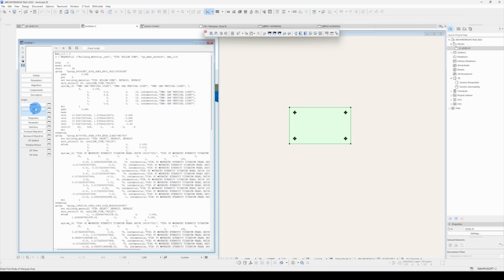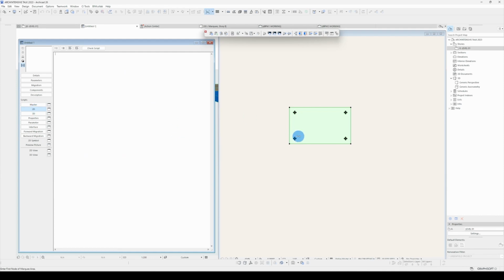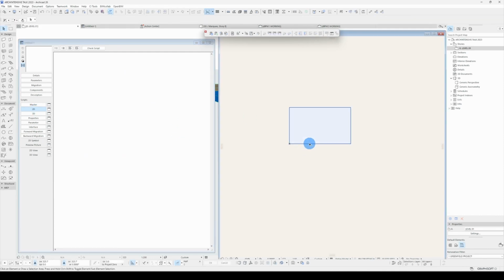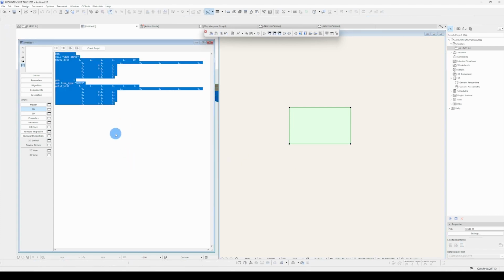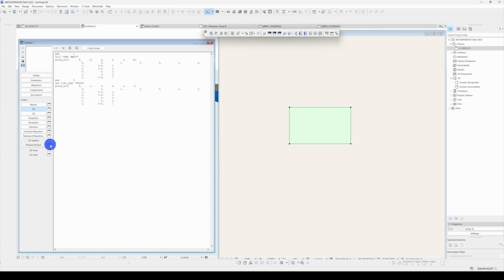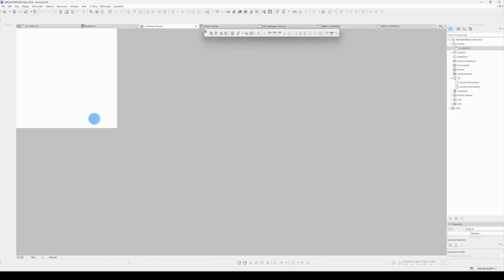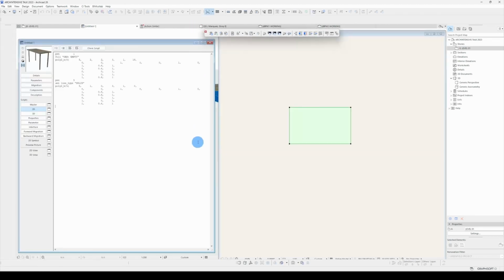The next step is the 2D window. So I click on 2D and I only want to drag in the stuff I want to appear in my plan. So I don't have my legs selected in this one. Click on the desktop, make sure my drag icon is active. Hold, drag, marquee square has appeared next to my mouse cursor, release. There's my script. And then I'll put in my preview picture. Save it.